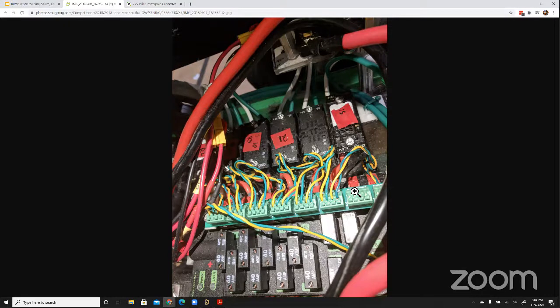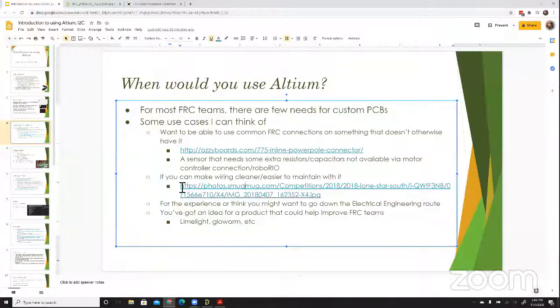That works for us because we tend to put our motor controllers physically near the PDP. For other teams that move your motor controller nearer the mechanism, maybe that wouldn't work as well. And we've been kind of tweaking this and messing with it a little bit. I think we could make this one bus and then just have a 12-inch stub or less come out to the motor controller and still be under spec and be fine with that. There's plenty of CD conversations about all of that.